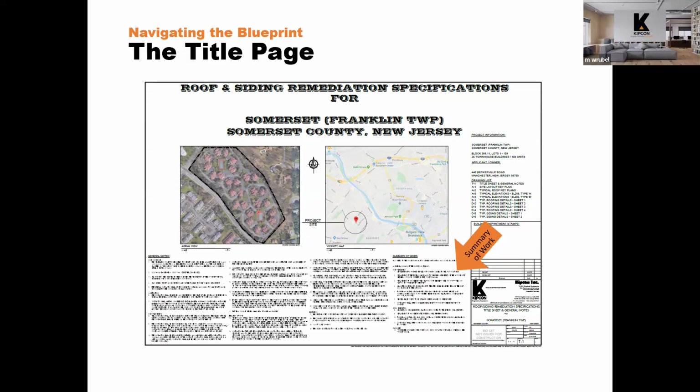that summary of work might include something like the contractors executing their general mobilization and setting up on site, milling of the top course of the pavement, making any base repairs, putting back an overlay of new pavement, making any repairs to the turf. So it's very general information step by step as to what's going to happen during the construction that's shown in the plan set.